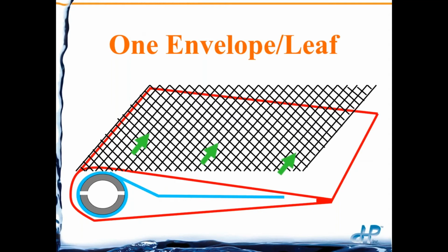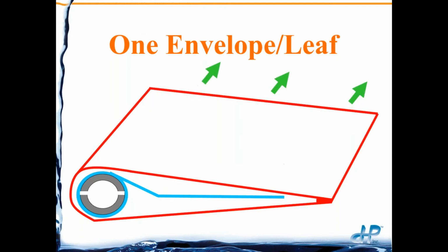That water comes in and goes through, exits out the concentrate. Due to the pressure from either the high pressure pump or the city, the water passes through the membrane, gets into the permeate water carrier, goes through those channels down to our permeate tube, and then exits out whichever end is easiest for the plumbing or the piping coming out of the RO system.